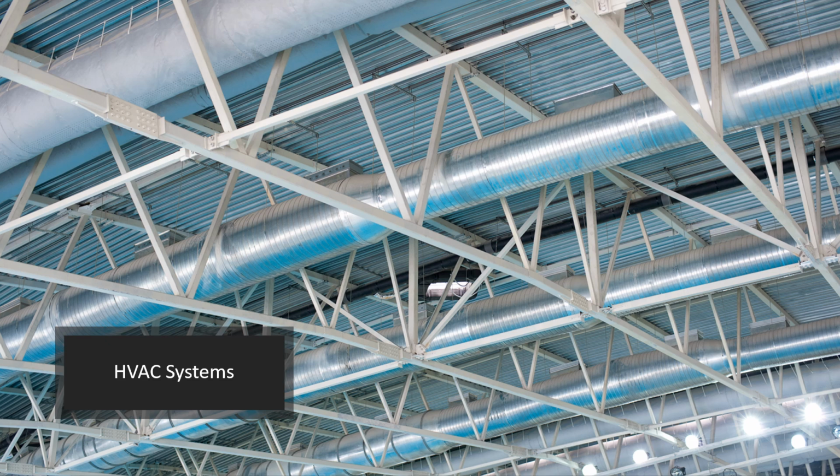Now, design considerations for HVAC in a sports facility really require temperature control. A sports facility requires precise temperature control to keep the environment comfortable for athletes, spectators, and staff. That involves selecting HVAC systems capable of adjusting quickly to changing needs, such as during events or practice sessions. Large arenas may need separate zones or HVAC systems for different areas like spectator areas, playing courts, and locker rooms, to address the varying cooling and heating demands.